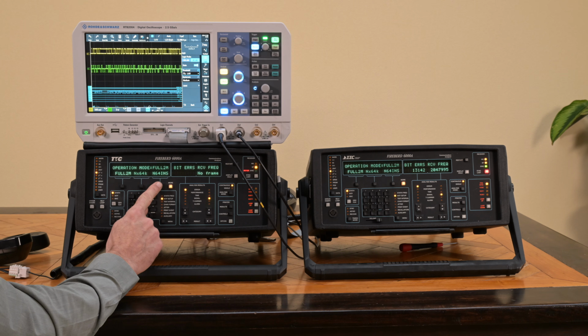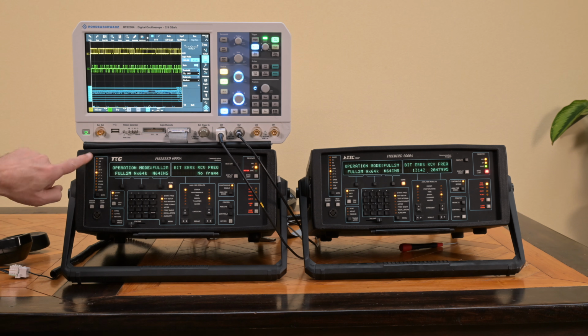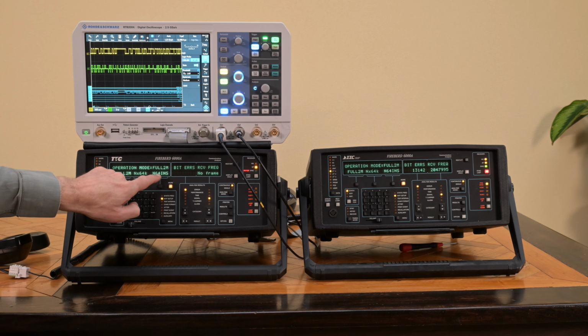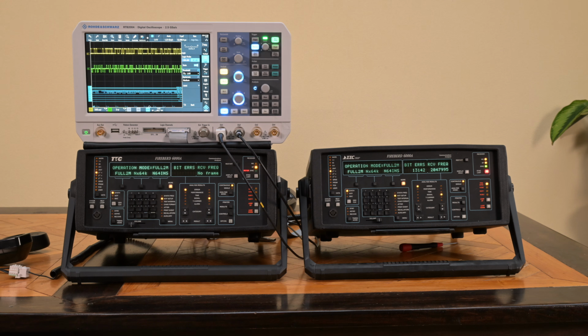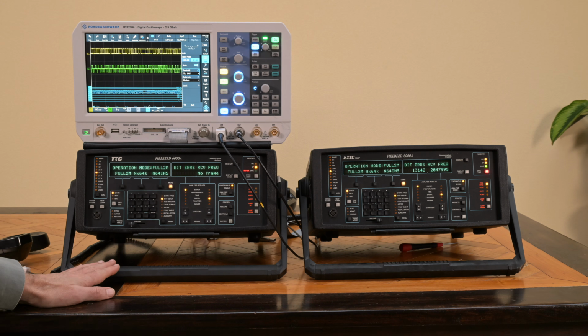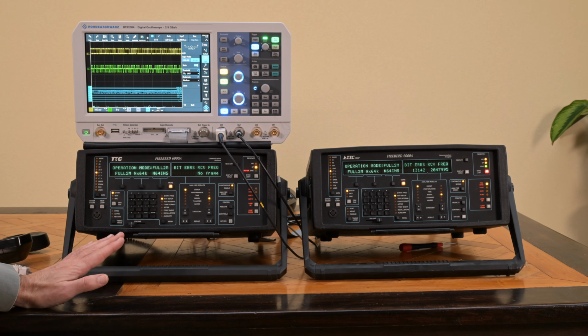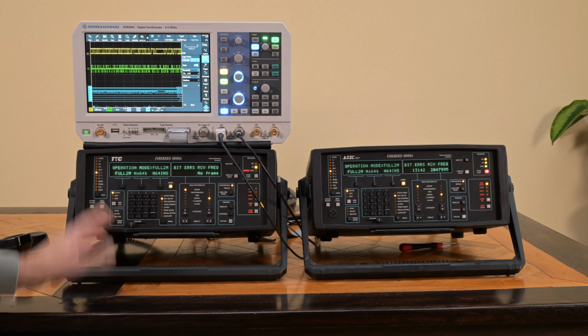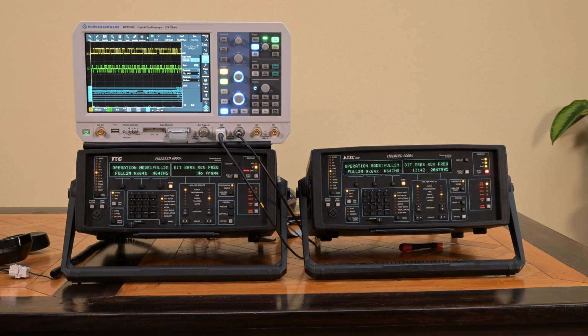I can insert one particular signal out of the 32 or so signals, so I can have a particular test signal on one or more of the voice channels, but not on the other channels, and then analyze them on the other side. And this makes this device very powerful because you could use it, for example, while it's actually operating 30 voice connections in a commercial environment. Connection 31 could be a test from the one Fireberd to the other one.